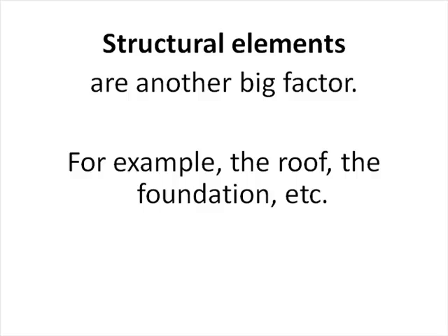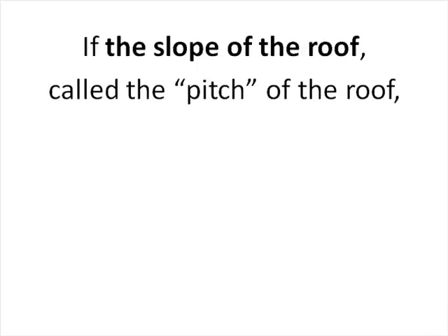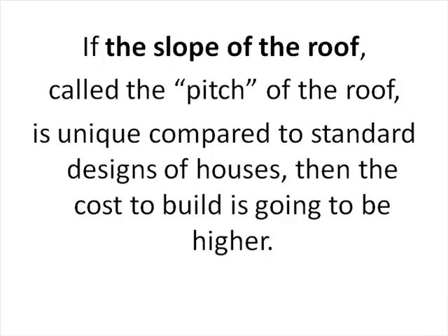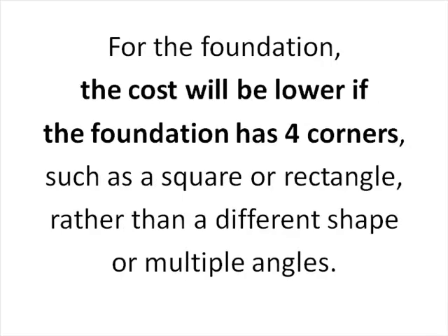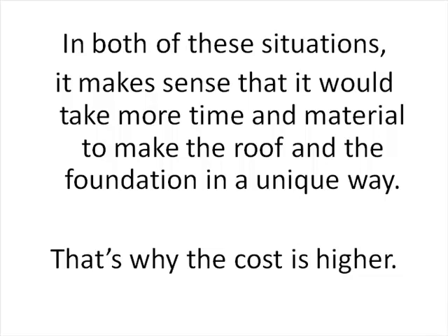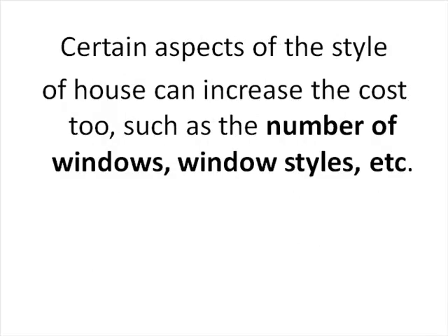Structural elements are another big factor. For example, the roof, the foundation, etc. Let's dive deeper into this. If the slope of the roof, called the pitch of the roof, is unique compared to standard designs of other houses, then the cost to build is going to be higher. For the foundation, the cost will be lower if the foundation has four corners, such as a square or rectangle, rather than a different shape or multiple angles. In both of these situations, it makes sense that it would take more time and material to make the roof and the foundation in a unique way. That's why the cost is higher. Certain aspects of the style of house can increase the cost too, such as number of windows, window styles, etc.